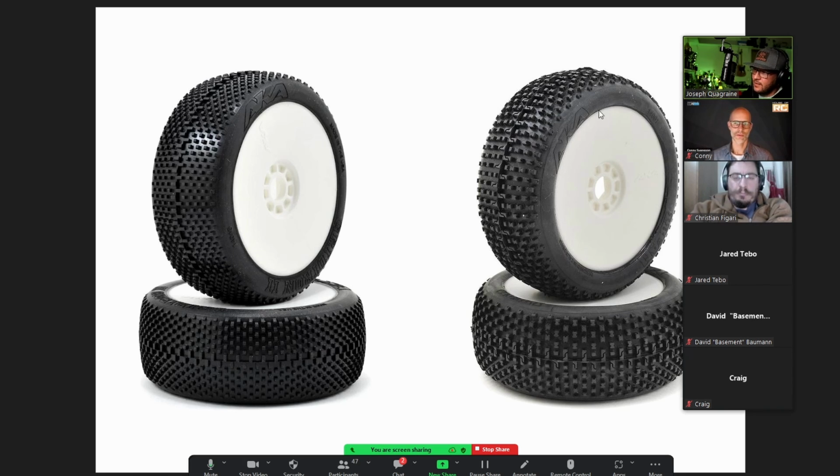Then the I-beam here on the right, this shape of the carcass was a lot rounder. The sidewall is round. It was bigger. The pins are also bigger. So this tire allows for a lot more flex and give, and this is more like that green curve that I showed you. So the maximum traction is lower, but you don't have to be as precise to get the most out of this tire. So this tire will be easier to drive.